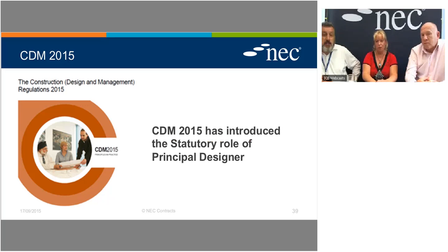CDM has introduced the statutory role of principal designer. They have to take a lead in the coordination, making sure that information is current, is correct, is appropriate. So that was the CDM coordinator. He's now gone. The problem used to be that the designer had to design out hazards and had to run the design, but the CDM coordinator also had to ensure the designer was doing that, and so did the client. And with three people responsible for it, everyone said, well, it's over to them. I've done my bit, but it's over to you, and it went wrong because of you. Now it's a lot more focused, one party responsible for one thing.